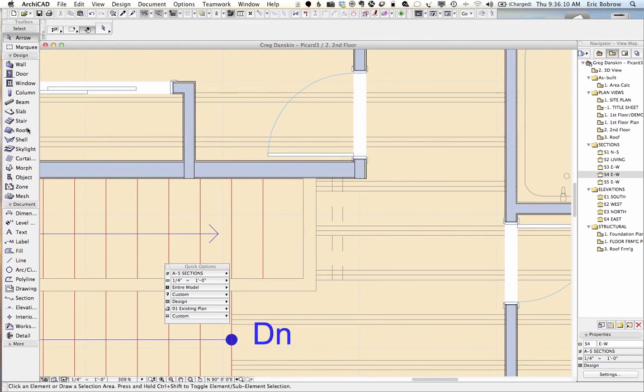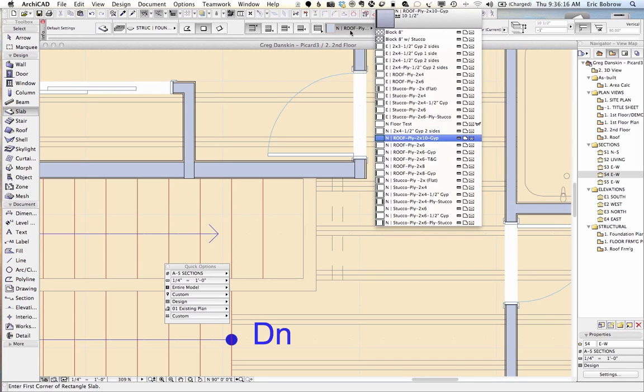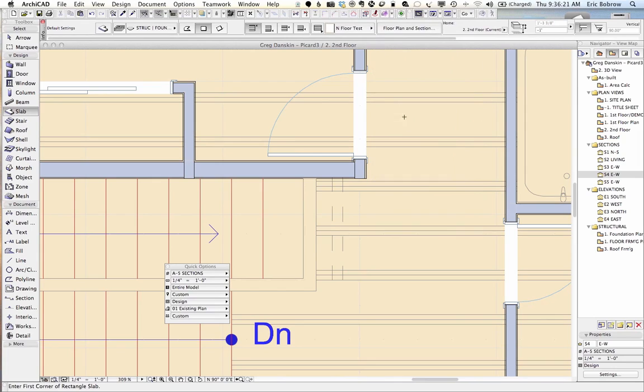And then I'm going to use the new slab, and we're going to pick this as a composite. We're going to pick the new floor test here. In terms of its reference height, let's just say that it's on the 0 of this story. We can adjust it later. And that would be potentially the top of the whole thing that we're looking at.